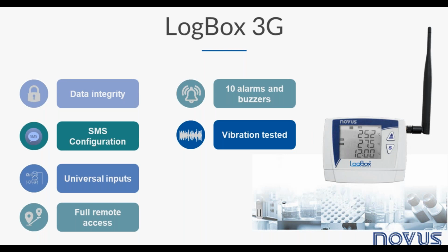It also provides two universal analog inputs for multi-sensor capability. We can set up to 10 different alarms on it. The built-in buzzer may be used for audible alert on alarm conditions. Most of the LogBox configuration can be done using SMS commands from the mobile phone. It is enabled to operate on trucks once it was submitted to vibration tests in order to comply with transportation environment standards.